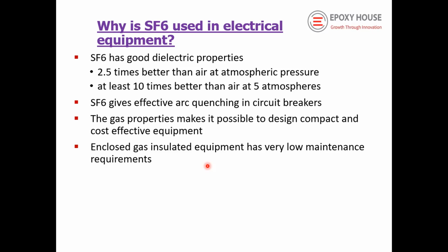Many utilities have tried to use it in their modern substations. But if you see, SF6 gas has a very high arc quenching property compared to other gases. This is the reason people are not able to easily change the gas into other gases.